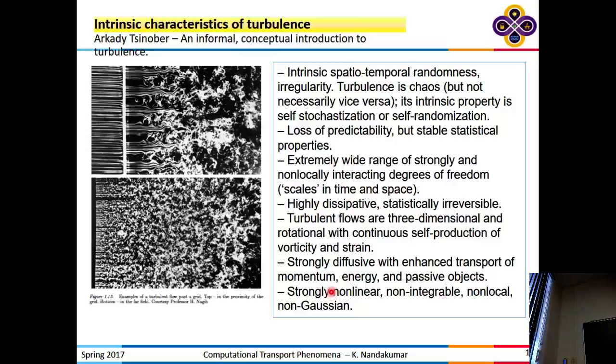So how do you generate this? You have fairly uniform flow that comes in. You put a wire mesh of a certain size. You control the size of the opening and the size of the cylinders in that mesh. And once the flow goes through the mesh, you'll find that each cylinder acts like a vortex generator because of the vortex shedding phenomenon. And you find flows that are becoming highly turbulent. Then you put a probe here, like a laser Doppler anemometer or a hot wire anemometer, and you gather data on the fluctuating velocities. Okay?